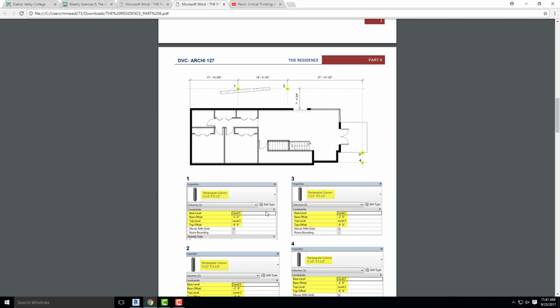And what we're going to do is we're going to choose architectural columns. Now the difference between architectural columns and structural columns, which you'll have the options of placing both, is architectural columns are very basic. They're basically extruded squares or extruded cylinders. Okay, so if you're looking for a more simplistic look. Now if you click on structural column, you can actually add any type of structural member, whether it be a 2x6 wood stud, a C channel, an H channel, whatever you want, any type of actual structural element that exists in real life. Okay, and we're going to learn how to upload both of those.